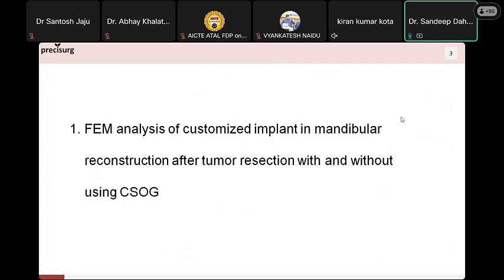So based on this, suitable constraints are selected. Also, two implants are assembled in such a way that the metatarsal implant has an angle of around 46 degrees with the surface. That is because the maximum load is applied on the metatarsophalangeal joint at this angle. Because of that, this arrangement has been provided. Also, around 545 Newton force has been applied in the X direction. That data has been taken from the previous literature.